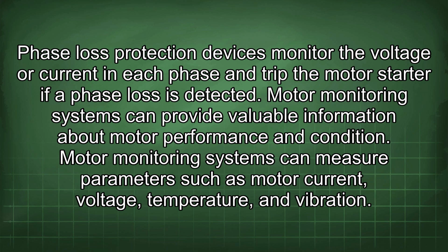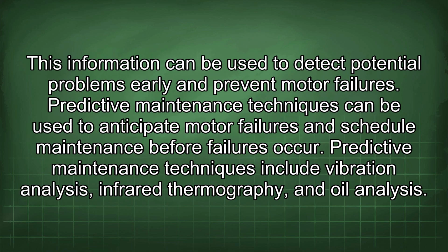Motor monitoring systems can provide valuable information about motor performance and condition. Motor monitoring systems can measure parameters such as motor current, voltage, temperature, and vibration. This information can be used to detect potential problems early and prevent motor failures.